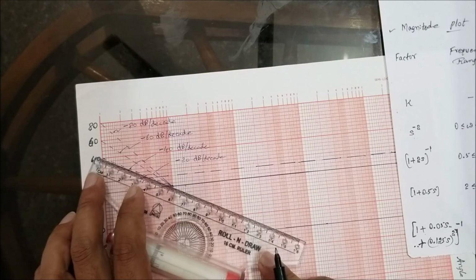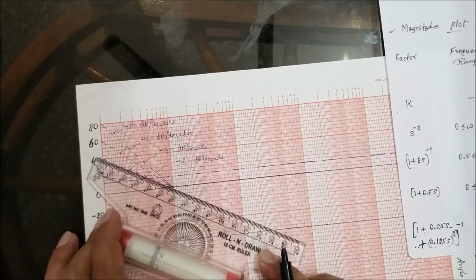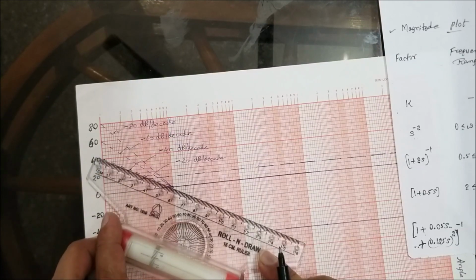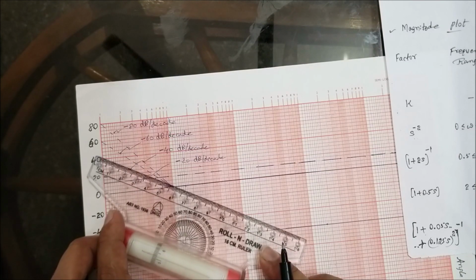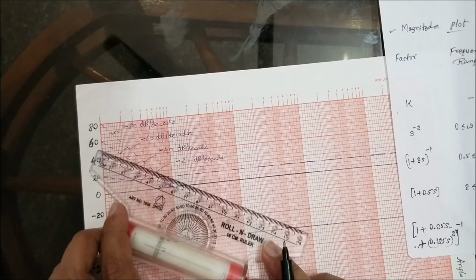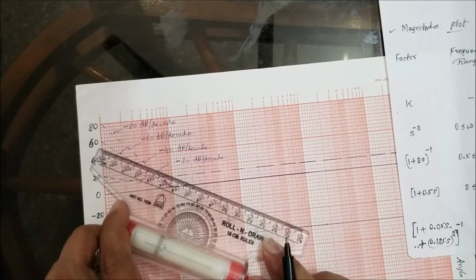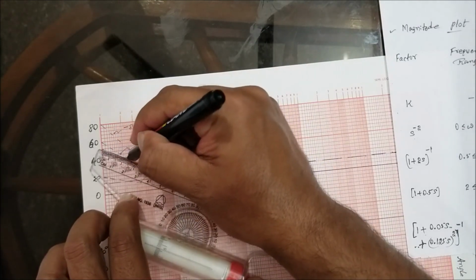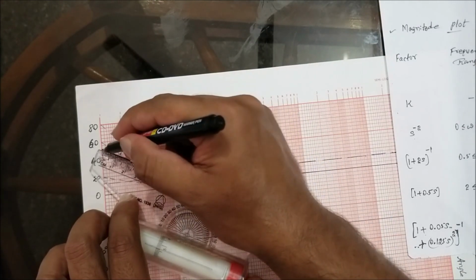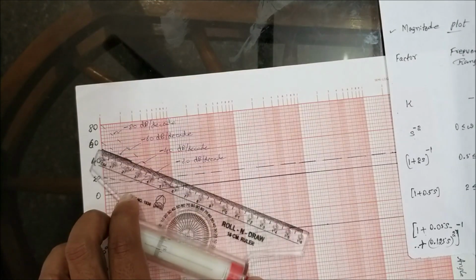You observed, now this should be shifted to 12 decibels. I am using a ruler scale for better accuracy. You people also use a ruler scale to avoid errors. So now shift this to 12 decibels at 1 radian per second. So I shifted, and now I got the starting line. Correct? So this line is minus 40 decibels per decade, which I got after shifting to plus 12 decibels.